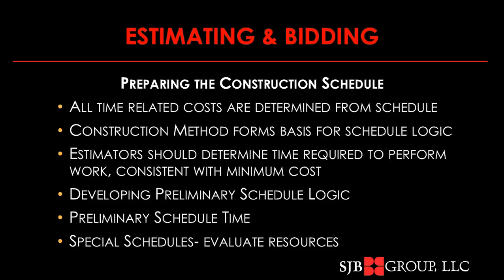Your equipment requirements may have a significant effect on how your schedule comes together. Ideally, you want to do the work sequentially, one part of the work following right behind the other. But you may need to consider the cost to demobilize and remobilize a piece of equipment versus the cost of leaving it idle on the job site.